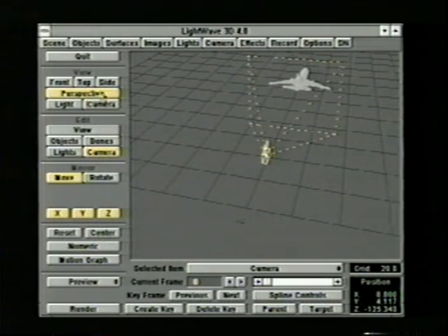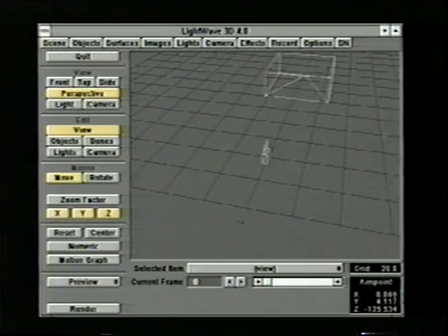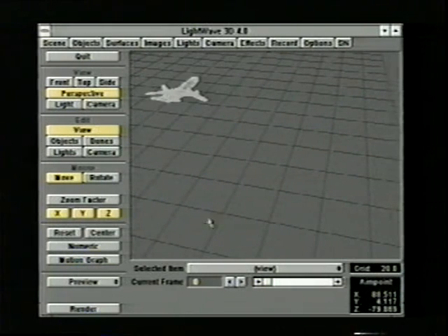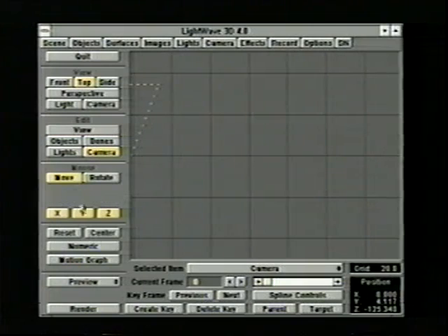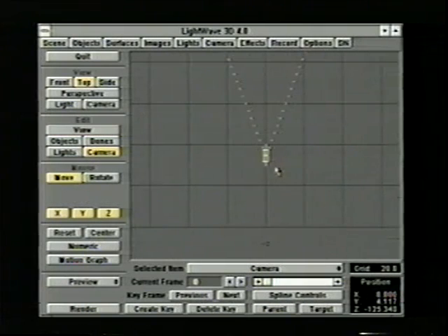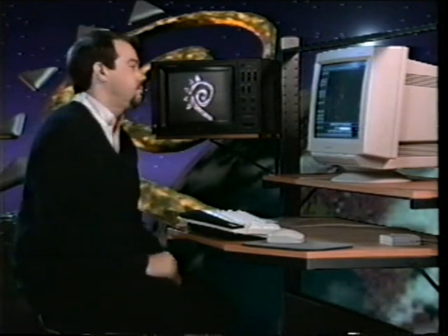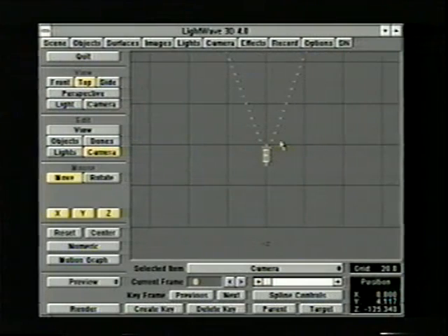And if I was looking at this from a different point of view, for instance, let's select view and move. Let's get the camera out of range. Let's just say we were looking at this from the top or the side point of view. Let's choose top. Again, with edit camera selected, hitting center will bring the camera into the center of the view. Note that this isn't actually moving that item, but it's moving the whole view to center on that. Okay, and just like with the objects we have move and rotate, notice we don't have size or stretch because we can't change that on a camera.